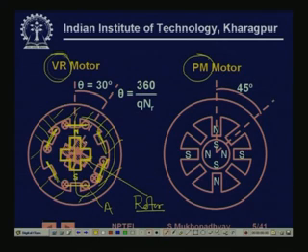If the rotor was inclined as shown by the pink rotor, then the reluctance of the flux path faced by these two coils would have been more. So, the reluctance of this path actually depends on the position of the rotor. That is why it is called a variable reluctance motor. For any set of phases excited, the rotor will assume that position where the reluctance of the flux path is the least.